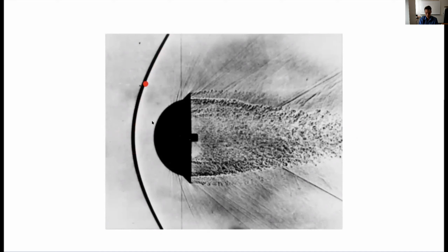And we actually pass through a whole range of oblique shocks here, all the way out to a Mach wave. But in general, this shape is going to give us a lot of drag. And again, that's going to occur anytime we have a blunt shape. But even with a sharp shape, at some point, it's going to occur eventually as we increase the Mach number.